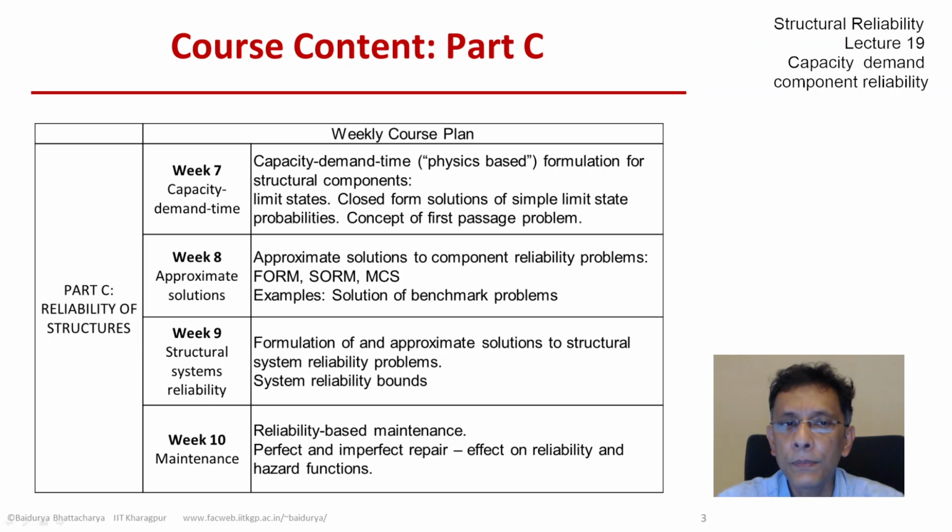Then we want to end part C with reliability based maintenance. So we're going to bring back the time to failure based approach once again, but that will be derived from the capacity demand approach. So that's where the capacity demand time is the central theme of this part. And we'll discuss effects of repair and how that affects the hazard function and the reliability function.